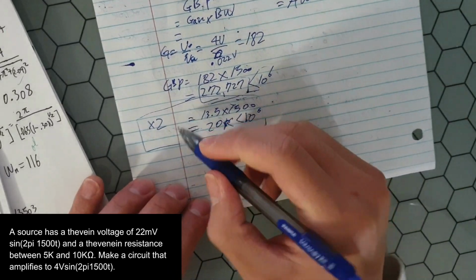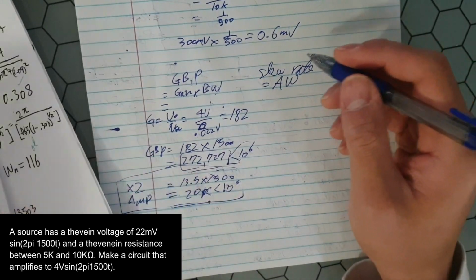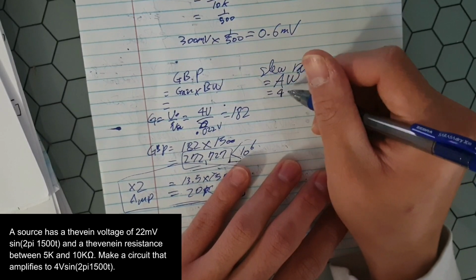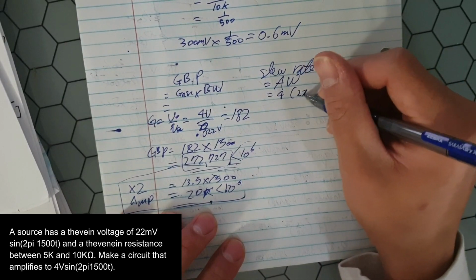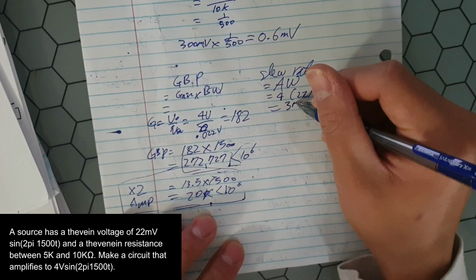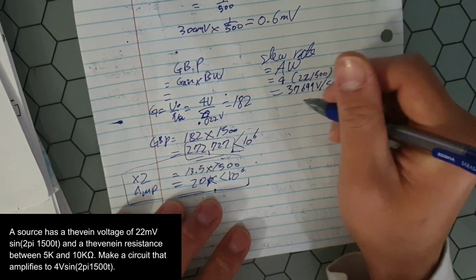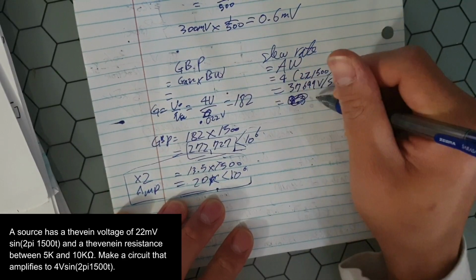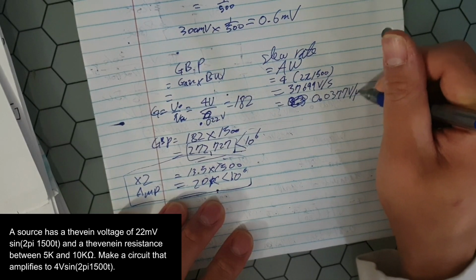Now that we know how many op-amps we can use, let's check the slew rate. Slew rate is just the amplitude, so 4 volt times omega, which is 2 pi 1500, and we should get 37,699 volt per second. That is equivalent to 0.0377 volt per microsecond.